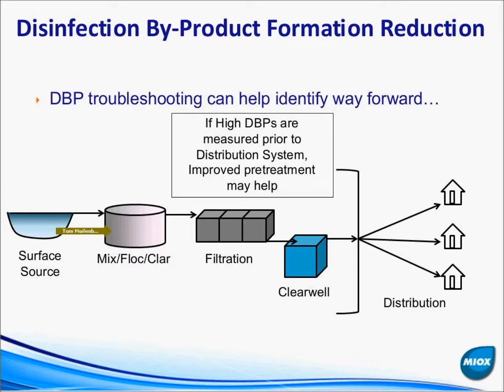You'll go into some sort of a clarification and coagulation process. So it might be a traditional flash mix, rapid mix, followed by flocculation and clarification. This might be a solids contact reactor clarifier. It might be something like a cone-style system, like a Claricone. After that, the settled water will typically go to granular media filtration of some kind. Alternatively, you might be looking at something like ultrafiltration at that point. There are a number of systems out there that have a pre-treatment prior to microfiltration.